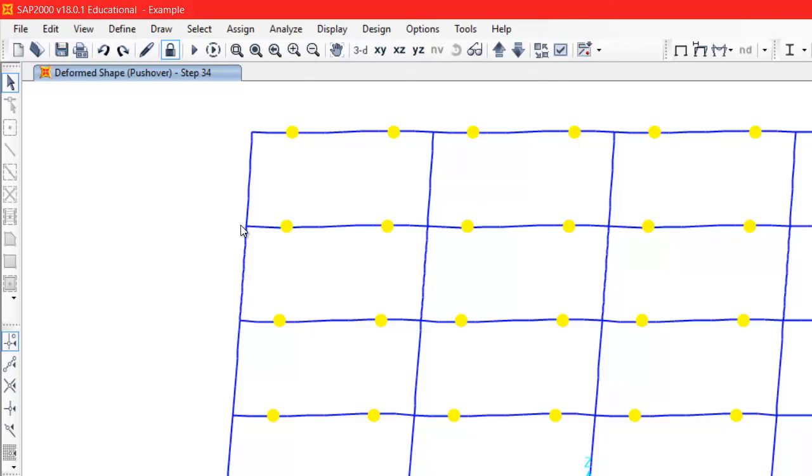It's an equivalent frame. What section properties would you take to get this frame? We discussed this when we discussed the gravity frame. For the beam, it will be sigma I_b or sigma Z, so you have to sum up. You see how many gravity beams you have. How do you get the theta? Do we include a spring? You have to include a spring.